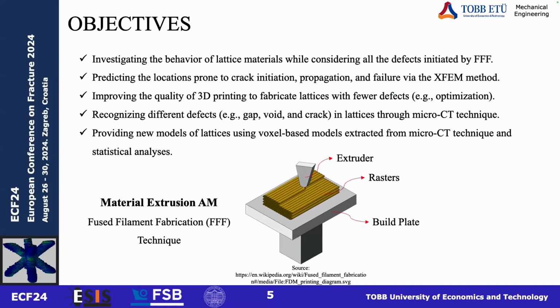Improving the quality of 3D printing to fabricate lattice with fewer defects, some sort of optimization. Recognizing different defects, for example, gaps, voids, and cracks in lattice through micro-CT technique. Providing new models of lattice using voxel-based models extracted from micro-CT technique and statistical analysis. And this is the general configuration of this method.